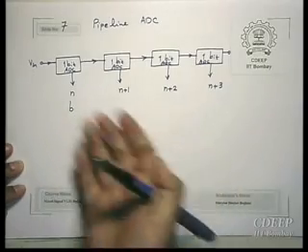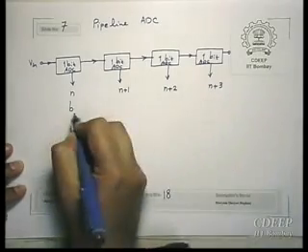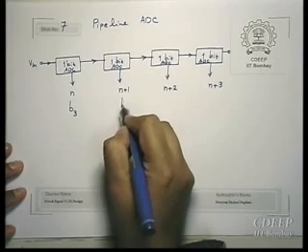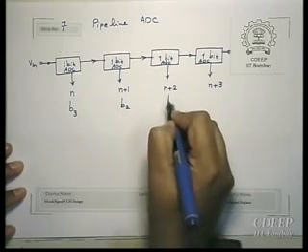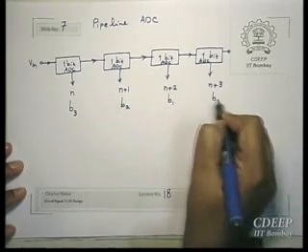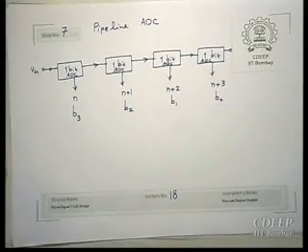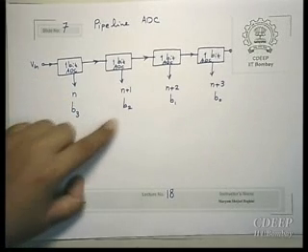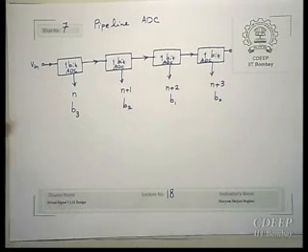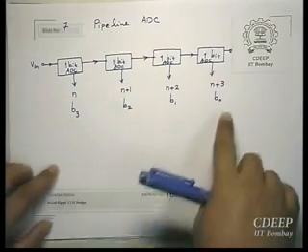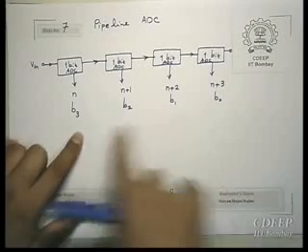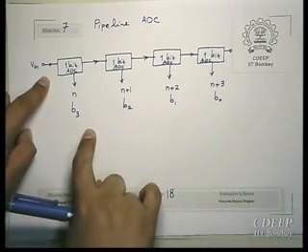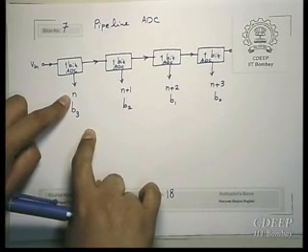So here I am giving a sample of 4 bits, so you will get B3 here, B2 here, B1 here, and B0. So what does it mean? It means that in cycle n you will get your B3, in cycle n plus 1 B2, and so on. Therefore when you reach cycle n plus 3, all bits are ready for the sample which was generated at cycle n.